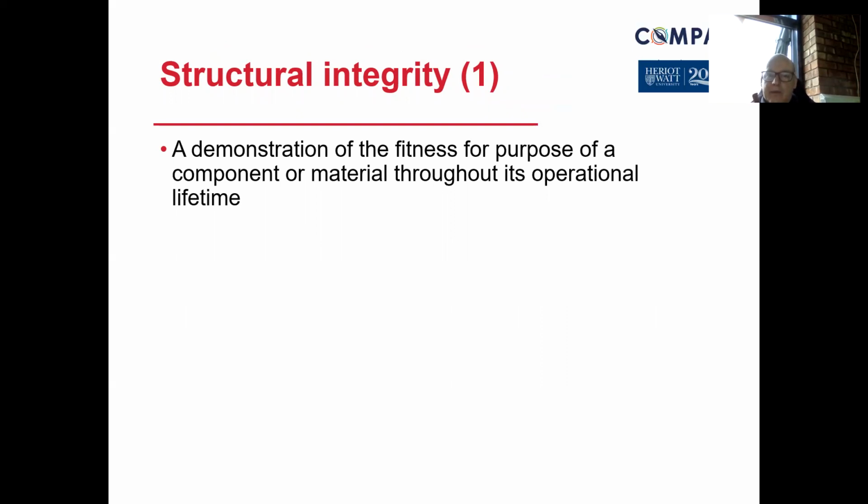And within that, fitness for purpose is a term that's used a lot in engineering and also under PUWER regulations for work equipment. When you demonstrate that something is fit for purpose, usually it's been tested, it's been tried, or historically it's got the research that backs that particular material on that pipe or on that safety valve or on that particular process. Stainless steel, for example, will be better than mild steel where there's potential for some of the materials going through it, or weathering on the outside of it, to cause corrosion, as an example.